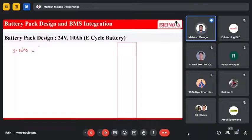Series is based on the battery voltage. We can go a slightly faster way: divide by cell voltage. The battery voltage is 24 volt, cell voltage is 3.6. Okay, 24 divided by 3.6 is approximately 6.66. So we take 7 in series.